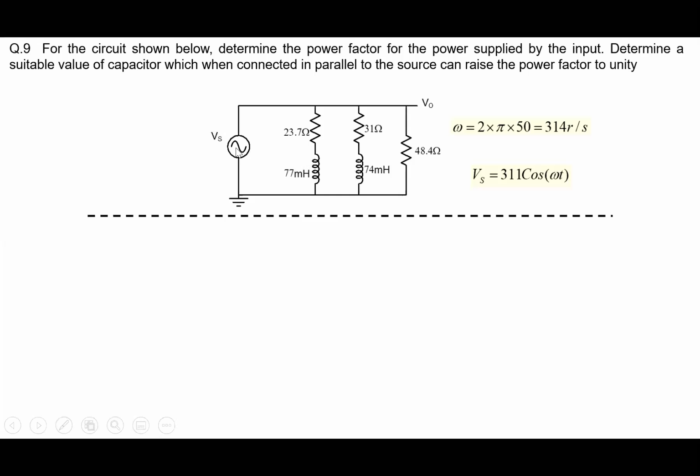Because note that the power station has to supply current. And here is where it becomes important, why we are focusing on power factor. So with a 90 degree angle the power factor is 0, but current is being drawn from the supply. And note that the power station may be located hundreds or thousands of kilometers away. So there is a large current flowing in the power lines, which have a resistance. So there is power dissipated in the transmission lines.